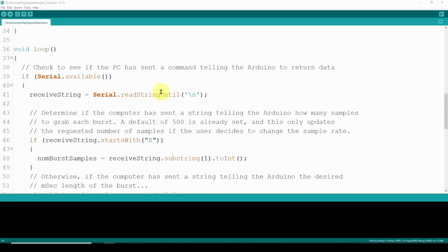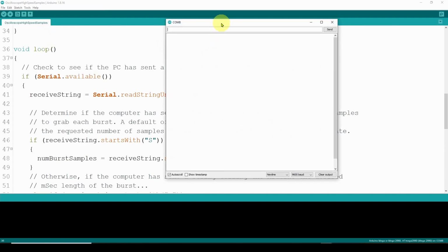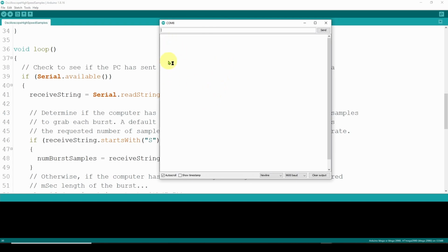And of course, if you are using an Arduino in your project, it is extremely important that you get familiar with and use the serial monitor. Control-Shift-M. When you have your Arduino sketch written, you can start up the serial monitor and monitor what it's sending over the COM port when it does a Serial.println.